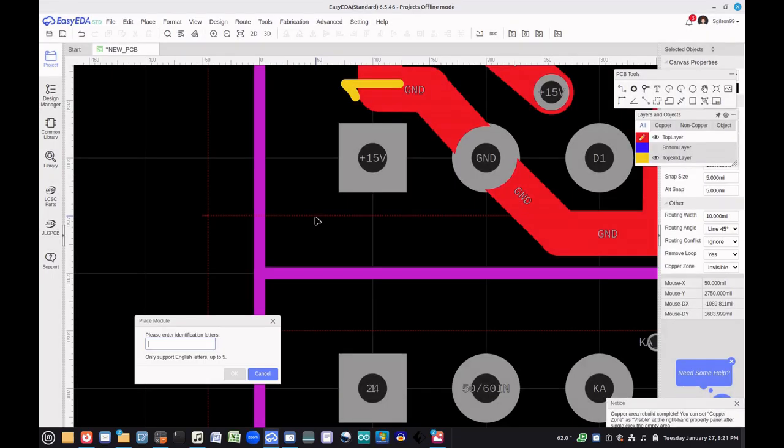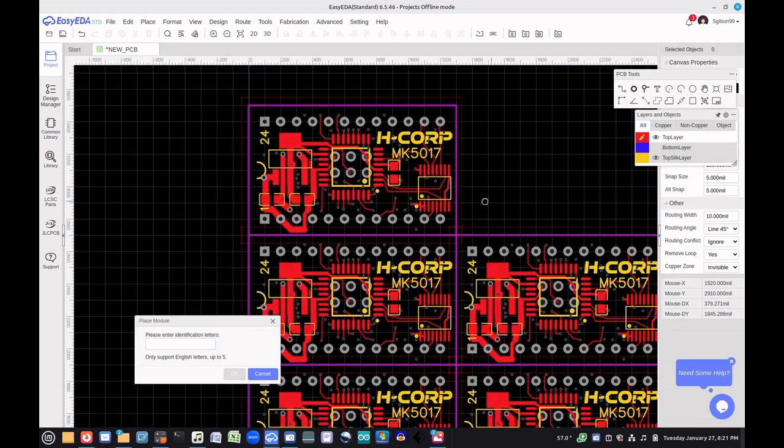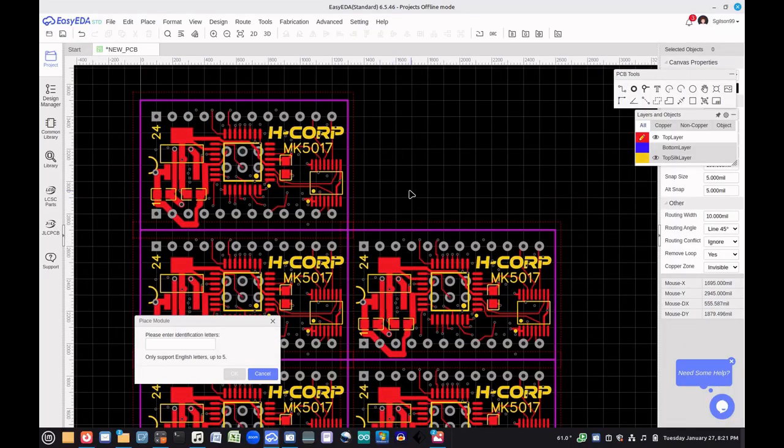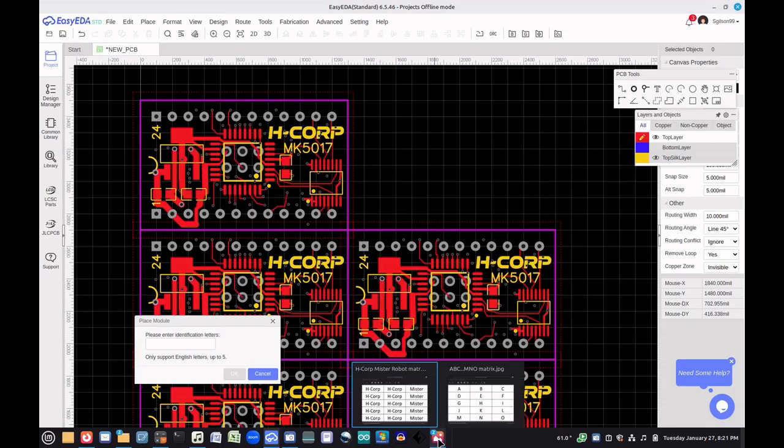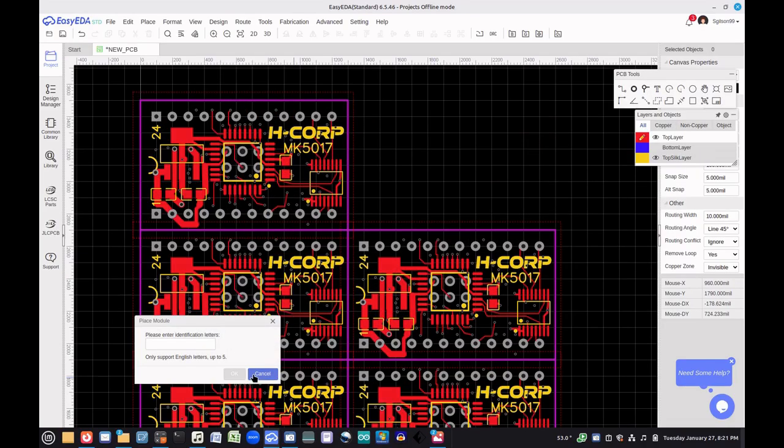So what happens is this whole file, the Gerber file, is going to be 15 times bigger, because you're having individual data for every instance, whereas normally when you panelize only one design, it just does one instance and then they replicate it there at the factory. So H is the next one.